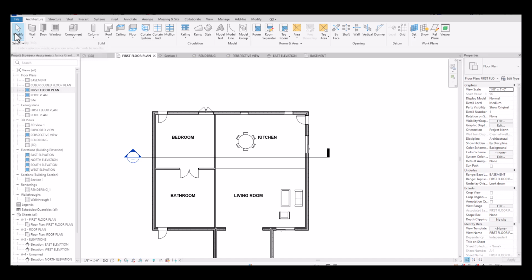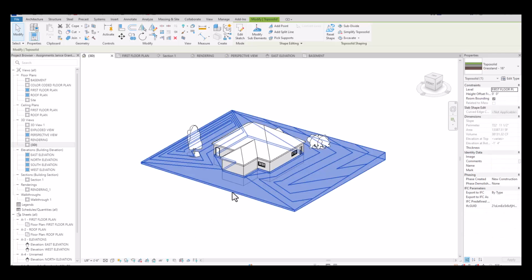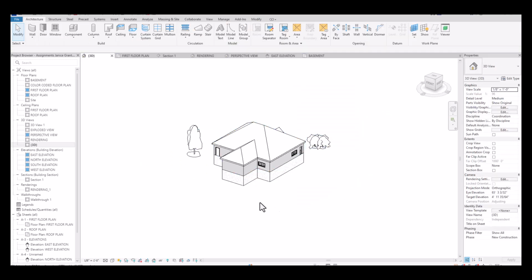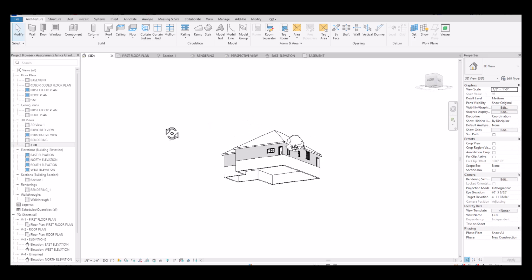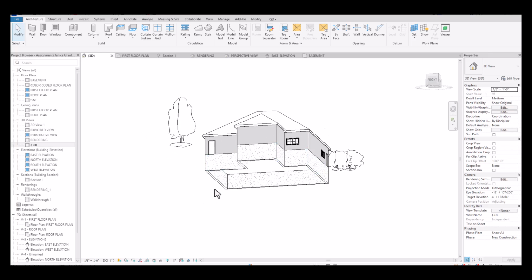I am going to now show you this in the 3D view. In the 3D view, we can turn off the solar panels that we had in the shadows. And actually, I'm going to temporarily click on the site, right click, and hide in view category. These are all going into that dialog box that is VG, typing in VG. So there it is. There's my foundation. Now, once I have that here, there's my foundation wall.